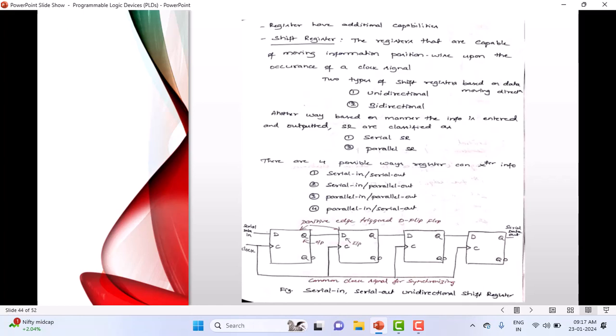Look at the truth table written there, the state table. It sees the input you apply and the present state and changes to the next state. Here for the 0, 0 condition, irrespective of the present state, it moves to the next state as 0, 0. Same thing here, 1, 1. Regardless of the present state, it moves to 1. The data input is copied here.